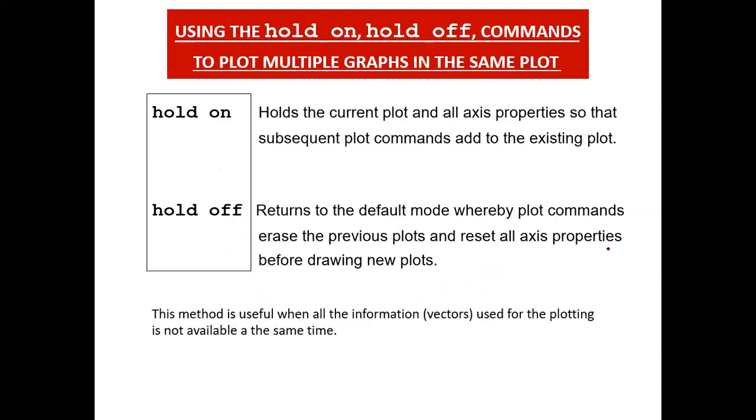Then next one is how we are going to use the hold on, hold off command. This is also very interesting, and we can use it for any type of multiple graphs in the same plot. Hold on means we keep working in the current plot and all axis properties, so that subsequent plot commands add to the existing plot.